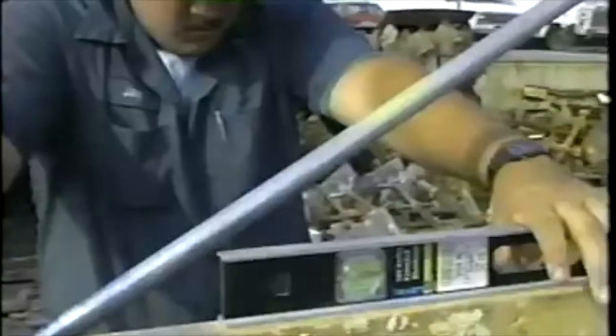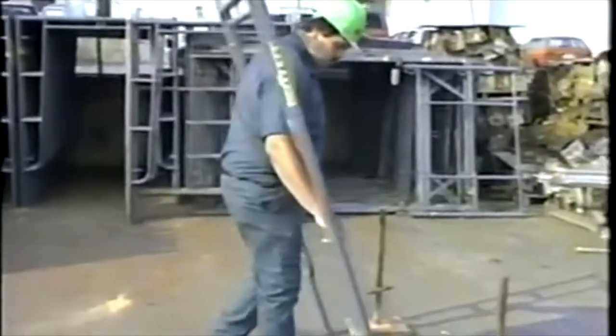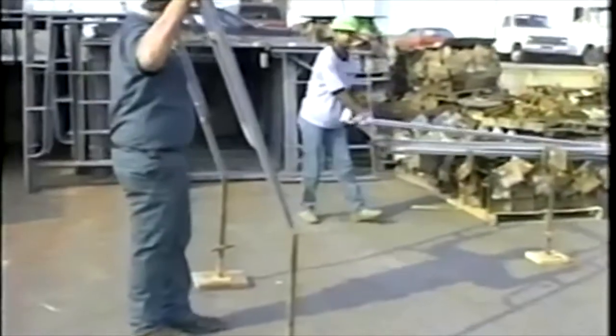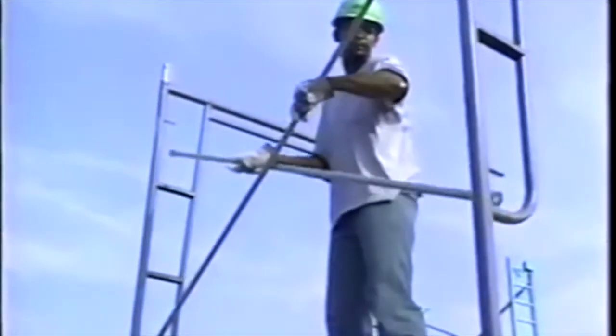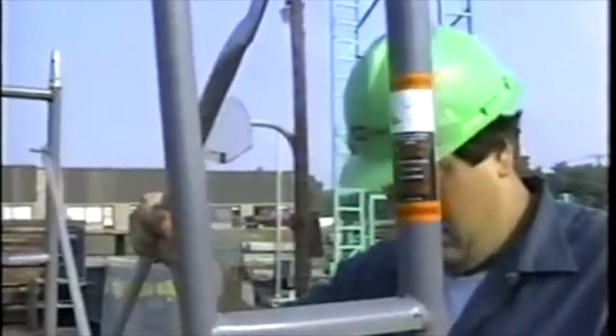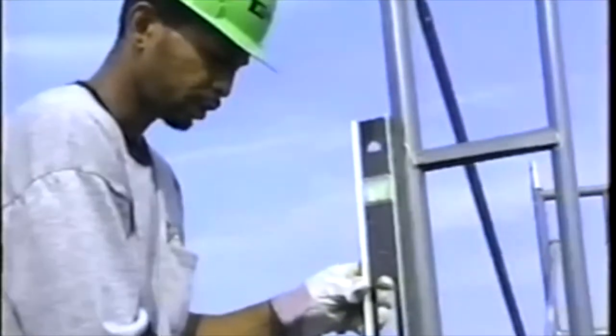Let's first look at the tubular metal frame scaffold, the most popular and widely used type of scaffold found on construction sites today. The tubular welded or fabricated scaffold is a sectional frame type scaffold consisting primarily of end frames and cross braces. Scaffolds must be properly braced by cross bracing to secure the vertical members laterally, and must be of such length as to automatically square and align the vertical members. Proper cross bracing will also ensure that the erected scaffold is plumb, square, and rigid.